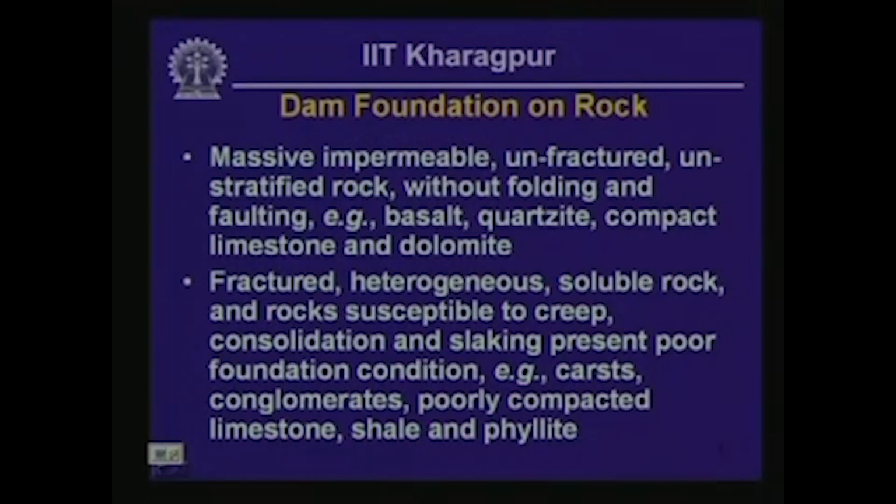In other words, if you test those types of rocks in a slaking test, a large proportion of the original weight is going to be retained after the repeated exposure to water, whereas rocks such as shales are expected to exhibit a remarkably small slake durability. So, that is in a sense what is meant by slaking.